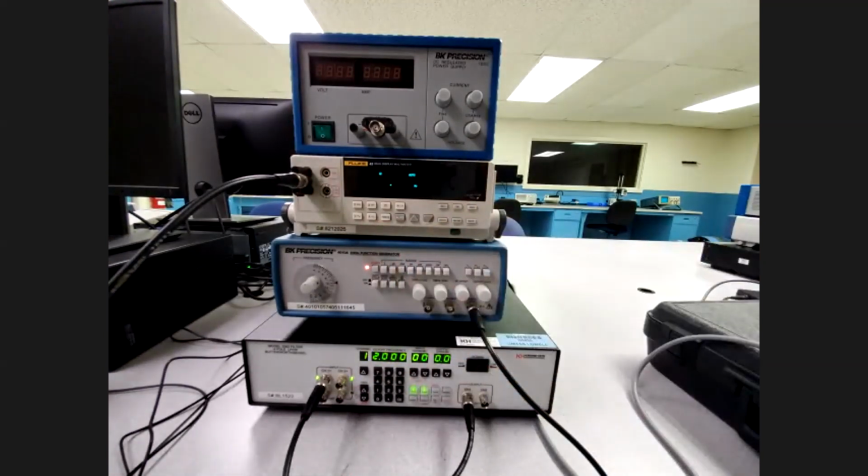We need to start at 100 hertz. Those are 100 hertz. I'm gonna leave it to magnitude and let's start collecting data. The first row goes like this. Voltage peak to peak from the oscilloscope is equal to 10.2. Voltage output from the multimeter, 3.53.